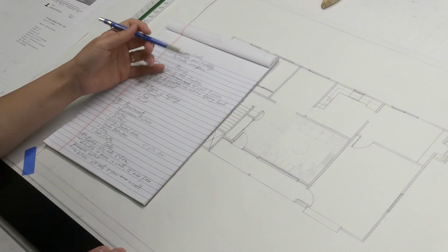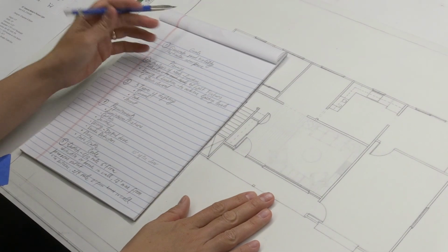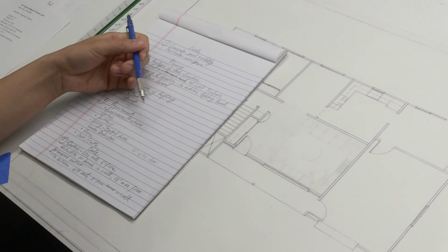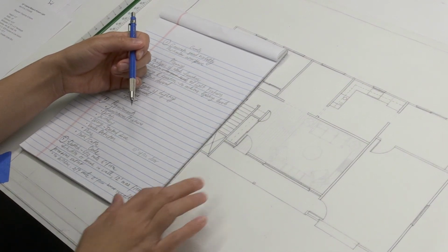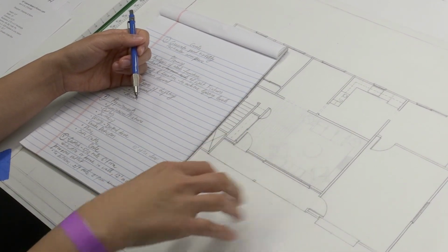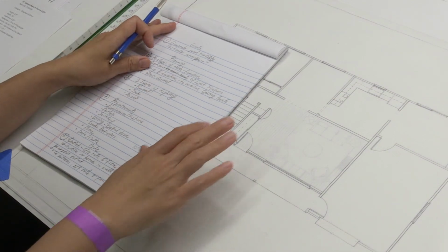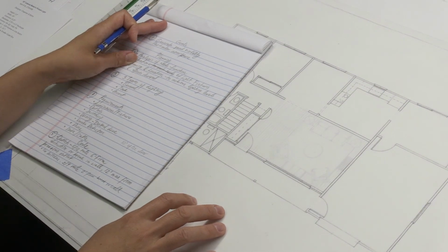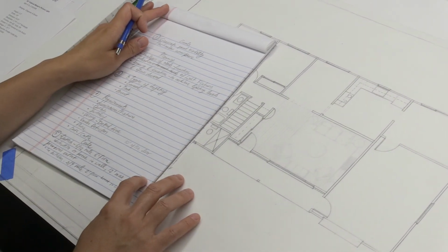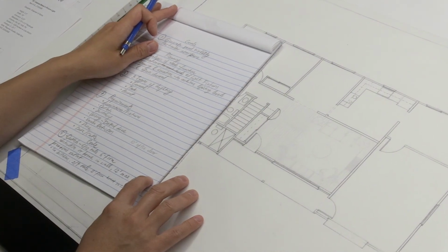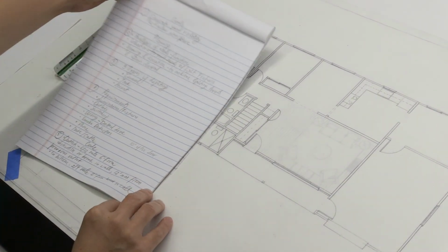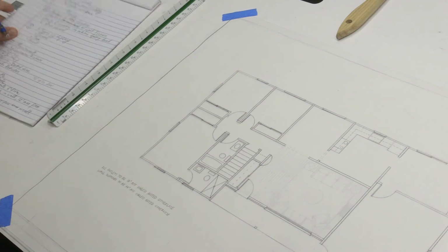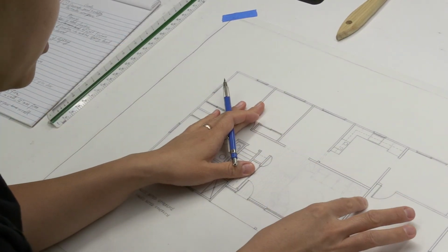Also, the requirements you have to have on your electrical plan are luminaires, that is fixtures, and then outlets, switching, and wiring, and wiring you show with a dotted line. I'm going to show you later. And then you need to add the smoke detectors wherever you need them, and phone and data cable. And also don't forget about the codes: the outlets, the 6-12 rule, and in the kitchen, you have to think about that also.